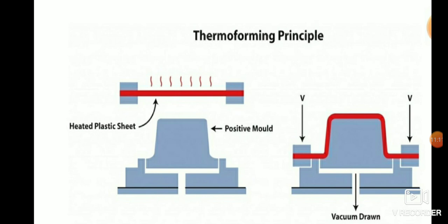Thick gauge thermoforming produces a limited number of products at a production cost below those produced by other processes such as injection molding. In contrast to the advantages, thermoforming has several disadvantages. The incoming material is an extruded sheet, with the extrusion process adding 50% or more to the cost of the formed product. Thermoforming generates substantially more trim than the other processes, and that trim must be ground and re-extruded at additional cost.